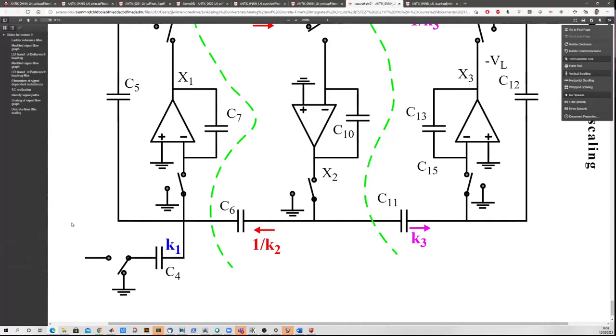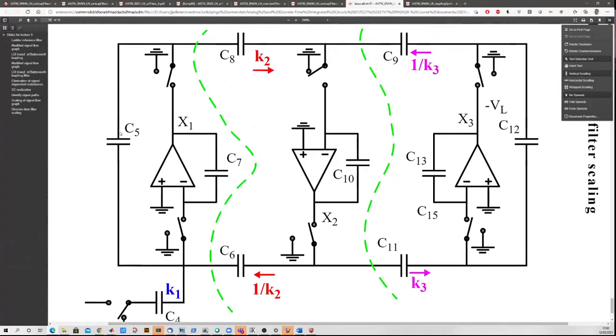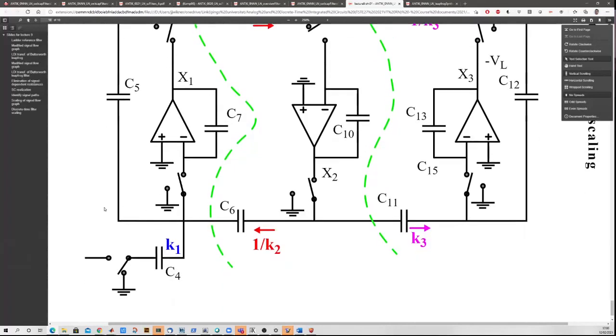So say you have 1 volt here, for example, what's the implication on the voltage level of X1 at the output of this op-amp? It's a bit hard to say, we don't really know actually. So you have to investigate so you're not clipping the amplifier. So maybe you have 1 volt here and this guy tries to amplify to 2 volts. Then obviously it won't work. So you have to scale down your input signal.